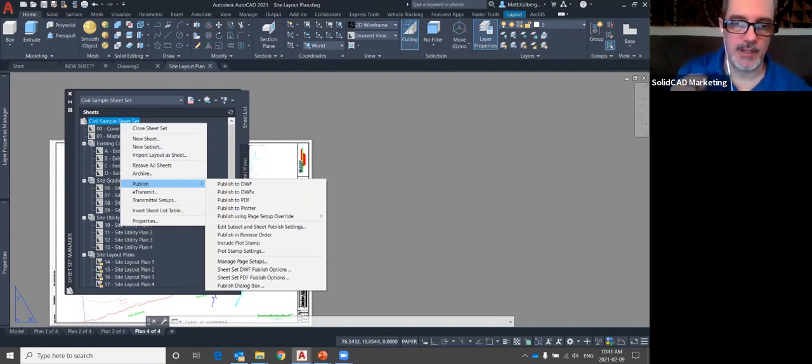Here's the scenario. You are the owner of a bunch of drawings and I am the sub-consultant. I ask you to send me a drawing, and you do. I open it up, and there's not much in it. I realize it's missing an XREF. So I call you back and say, hey, I think you should have attached the XREF to the email. And you're like, oh yeah, forgot about that. I'll send the XREF, I'll send the images, I'll send the SHX files, maybe because you have custom line types. See, sending a DWG isn't always just about that DWG. There are often references, XREFs, images, SHX files, CTB files, that kind of thing.